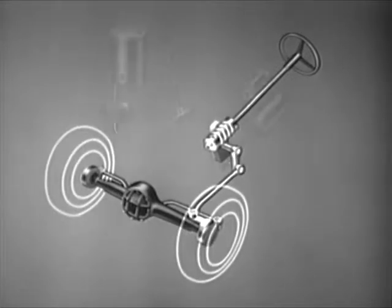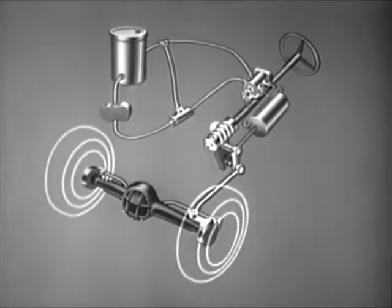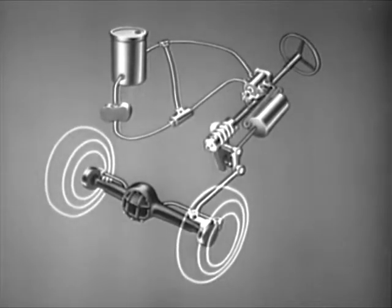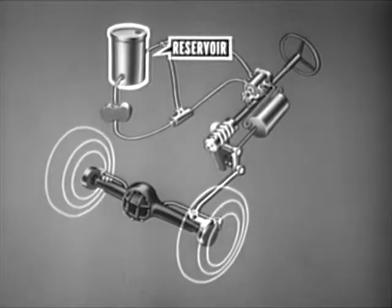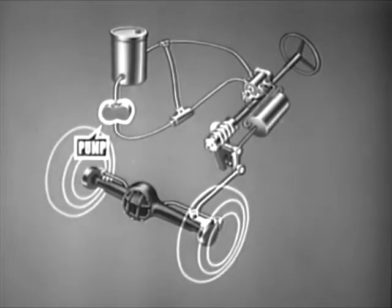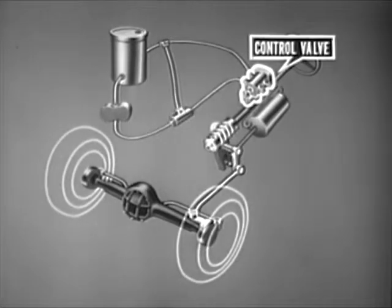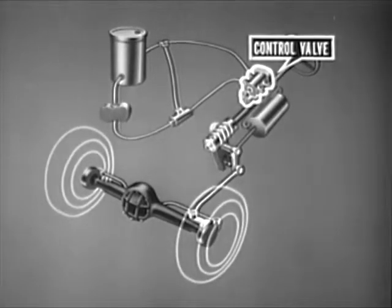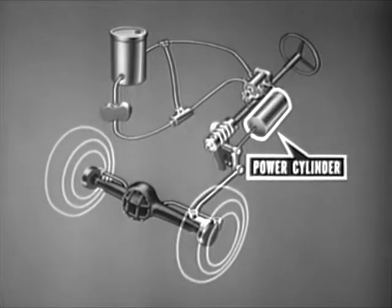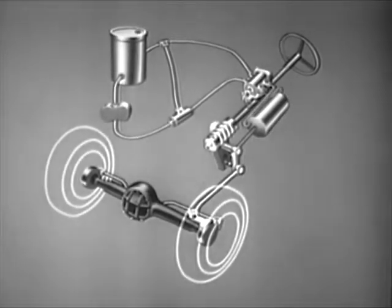To obtain the assist, a hydraulic system has been added to the cam and lever mechanism. The hydraulic steering system is made up of 5 major components: the reservoir, pump, relief valve, control valve, and power cylinder. These components operate on the principle of pressure differential.